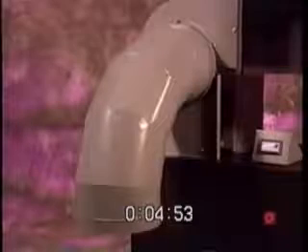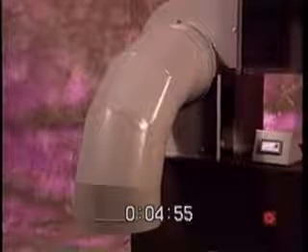This loss is often referred to as system effect. To make matters worse, it cannot be measured. To select and apply the fan properly, these effects must be considered, and the pressure requirements of the fan must be increased. Fortunately, there is a better way.